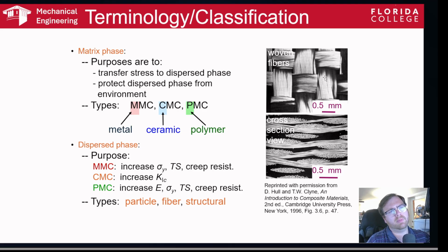Also, the material behaves differently when it's made in this manner. It's stronger in the tensile direction for the fibers, whereas the matrix material is more prone to cracking. Cracks don't want to move through these fibers because they're very high purity.